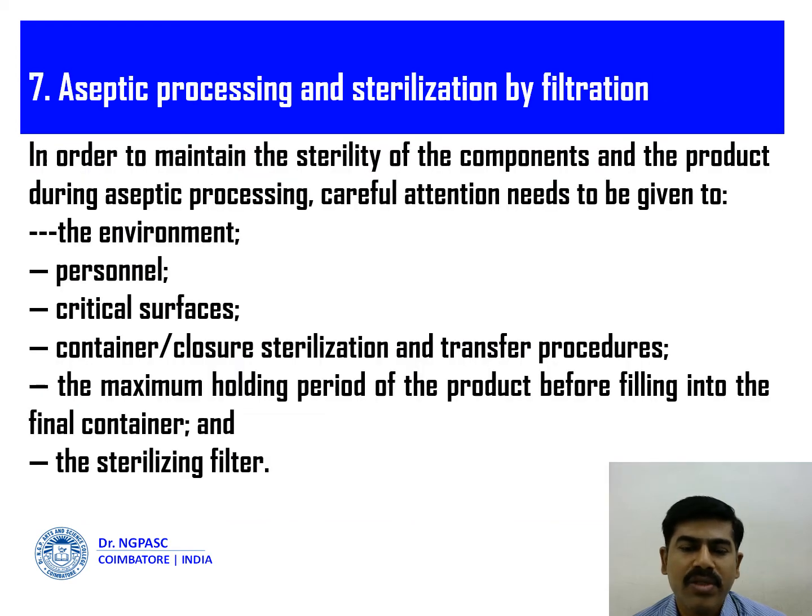Then aseptic processing and sterilization by filtrations. So in order to maintain the sterility of the components and the product during aseptic processing, careful attention needs to be given to the environment, personnel, critical surfaces, container closure sterilizations and transfer procedures. The maximum holding period of the product before filling into the final container and the sterilization filter.